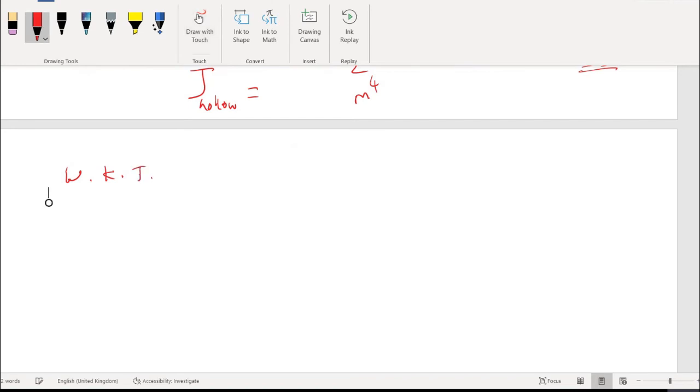We know that shear stress is equal to torque times rho over J, right? Now the allowable should be equal to the allowable in this case. What is that value? Better write down 100 megapascals, correct? 100 megapascals. Let me substitute.